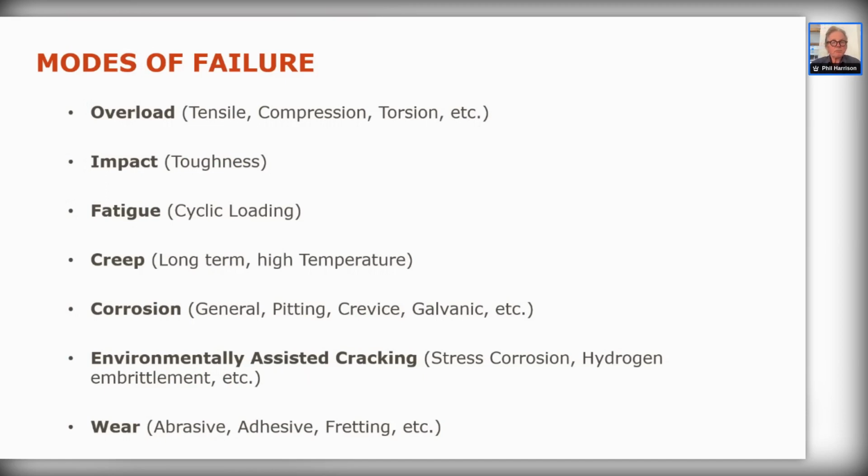And also, going back to impact and toughness, we've briefly covered ductile and brittle failure. Ductile and brittle failure look completely different. With ductile failure, you have warning of failure when it's going to happen. Things start moving. It is a very dull, fibrous type of fracture. Whereas with a brittle material, you get no warning. It can break without any deformation around it. So you'll look at something which has got no necking on it, nothing around it, and generally a shiny fracture surface. You could say that is a brittle failure.